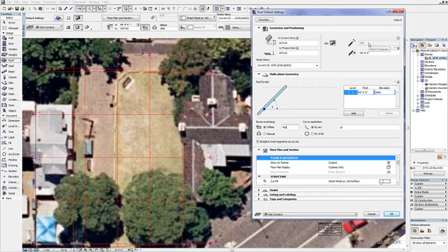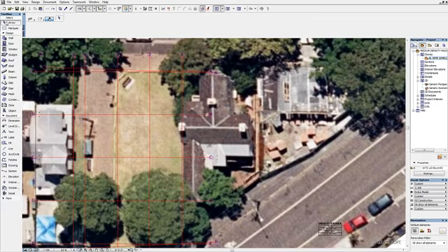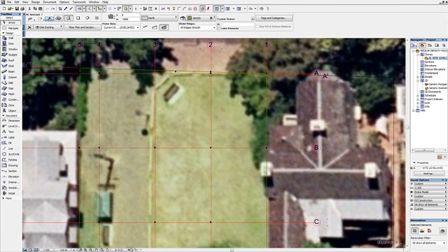What you had to do was build the roof on top of the existing wall, with no eave overhang, and then in plan use the offset tool, which we've seen a number of times already. Use the offset tool to offset by 450. If you recall, the offset tool is when you click on either a slab or a roof or a mesh. If you click on the edge and not at the dot, when you click, it brings up this little palette, and this is the offset edge icon.